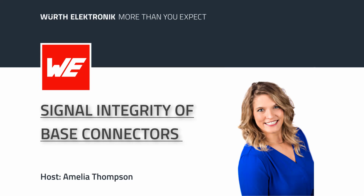Zero insertion force, commonly known as ZIF, and flat flexible cable, or FFC connectors, are extensively used in data PCBs. But there's currently no standard that precisely defines the signal integrity characteristics of these connectors, such as characteristic impedance, S parameters, and available protocols. So the aim of this podcast is to emphasize the importance of prioritizing signal integrity principles and to explain which frequencies can successfully pass through these connectors. We'll also discuss influential factors like FFC length, pitch, and connector type.